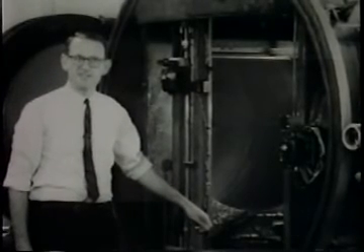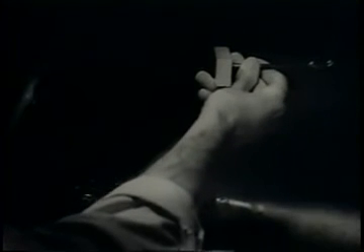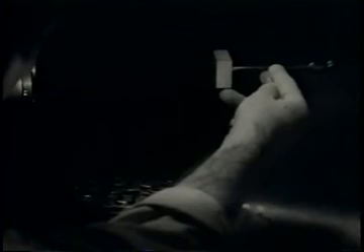It's mounted on a thin-walled stainless steel tube to reduce heat conduction between the model and the wind tunnel shell. We use a freely expanding jet again. Here is the nozzle, which is large enough to be in continuum flow.